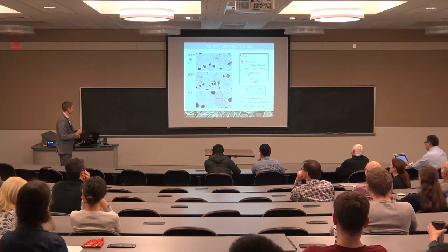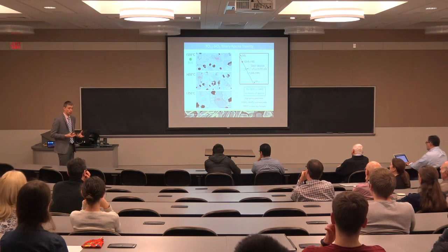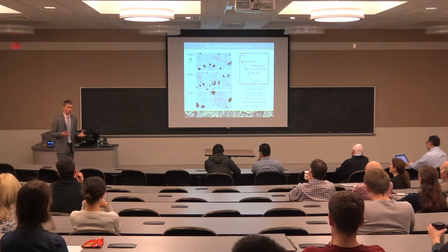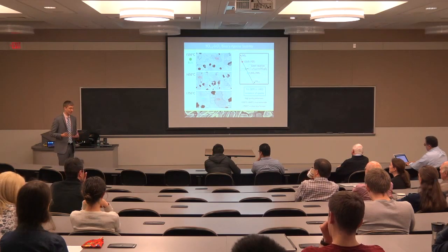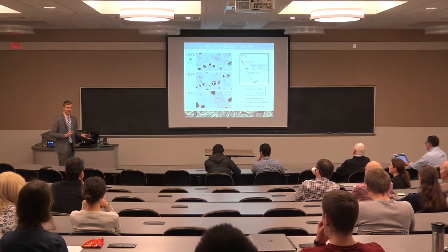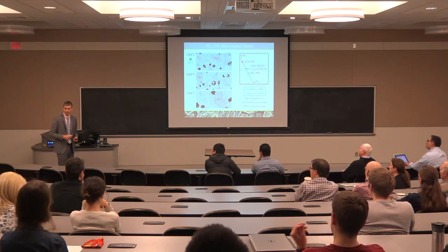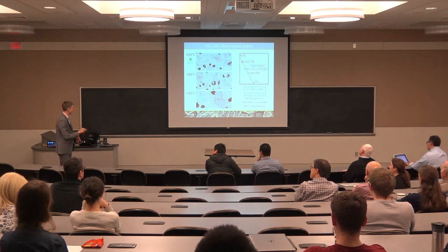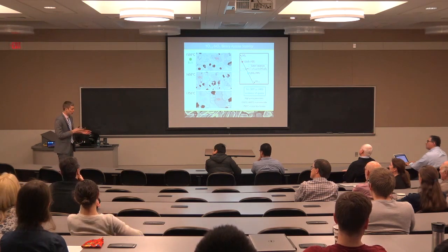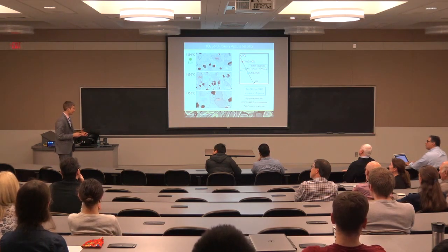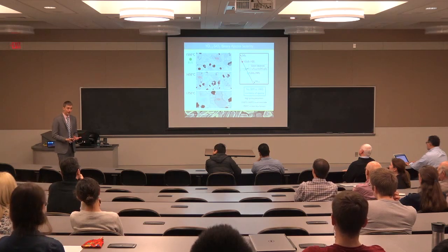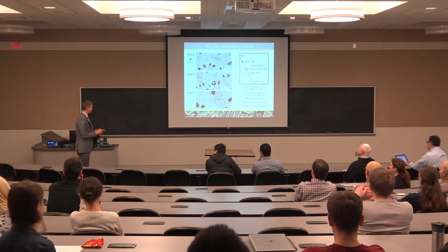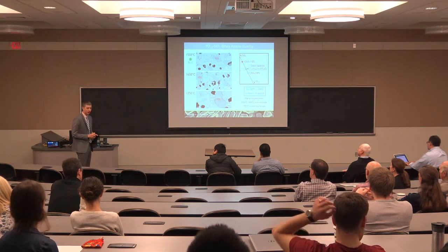And in fact, it turns out that the apatite phase loves to pull impurities from the environment. And so if you take a composition like this and anneal it in a dirty environment, a workhorse box furnace that has seen a lot of stuff, it'll pull enough impurities from that environment that you can start to form apatite. But you get a three-phase mixture then, which breaks the Gibbs phase rule if you just have a binary composition. And so we know then that can't actually be correct. So if we do the experiments in a really clean environment, we can get what I think is the correct result, which is just a two-phase mixture of these two phases, no apatite.